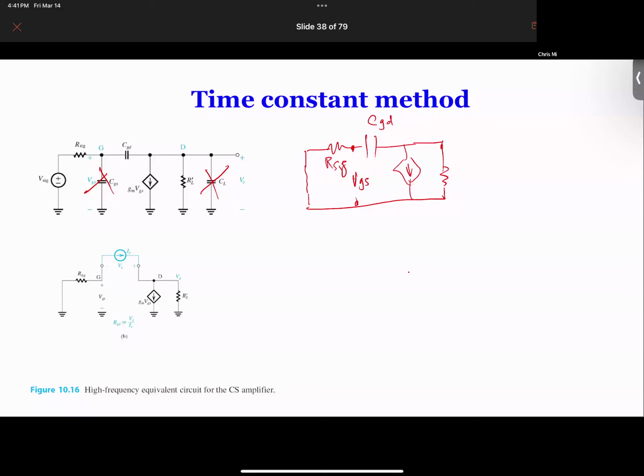So if you cannot find it, what we need to do is look at the Thevenin equivalent circuit, by finding the total resistance of the circuit. In order to find the total resistance, we're going to replace this little capacitor with either a current or voltage source.